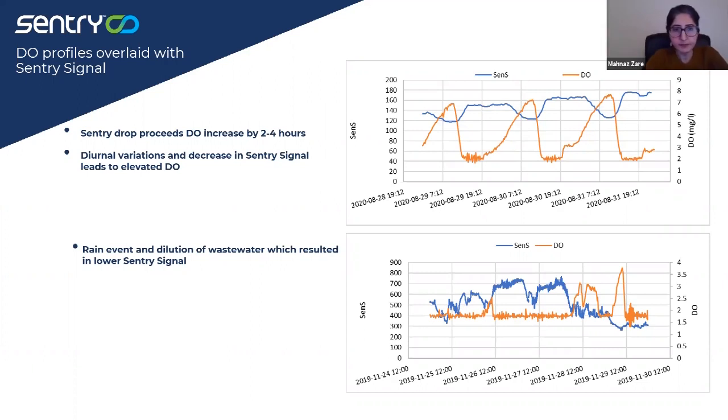Thank you, Selena. So the correct answer is option D. We are seeing higher concentrations of pollutants during the initial stage of rain, and the plot of pollutant mass against the volume can be used to identify first flush events. This plot is considered one of the fundamental concepts of defining or identifying the first flush phenomena in drainage systems.